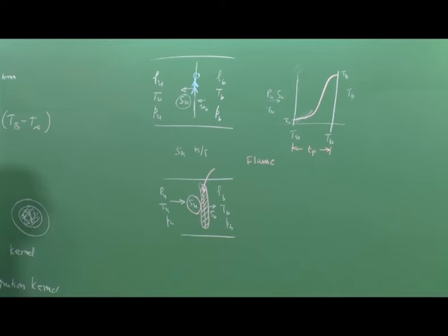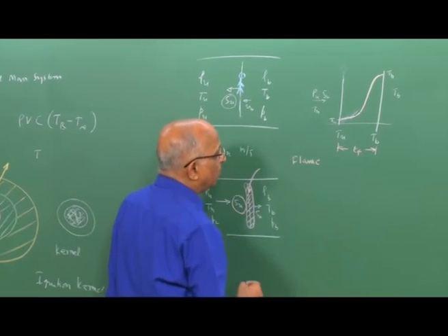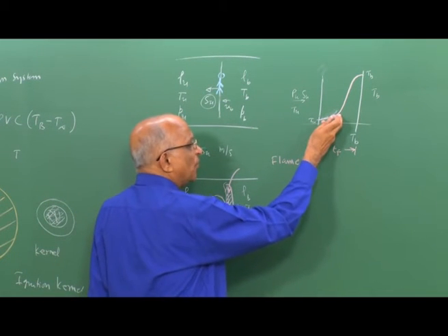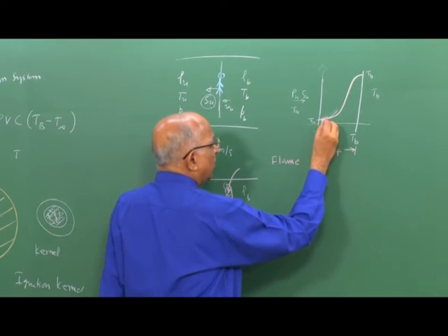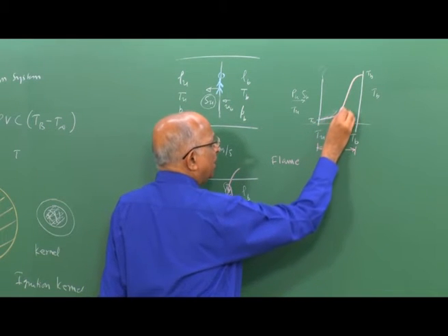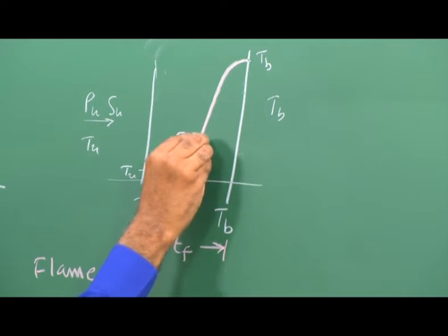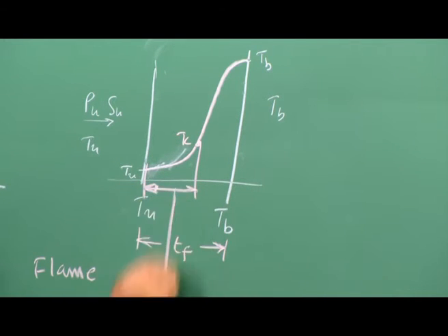If I use what little we have learned from the lumped mass system, we told ourselves that when the activation energy for most substances is high, initially I have something like a preheat, and the temperature increases to some value, let us say Tc. That is the zone in which the cold gases are heated to a particular temperature, which we called preheat.